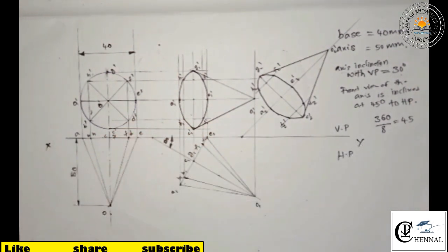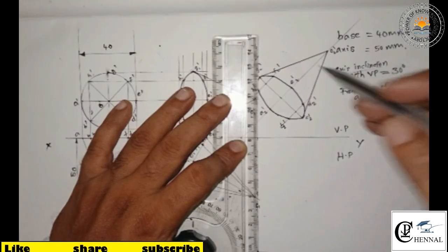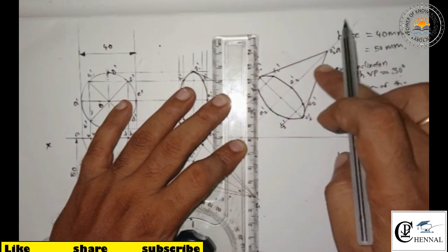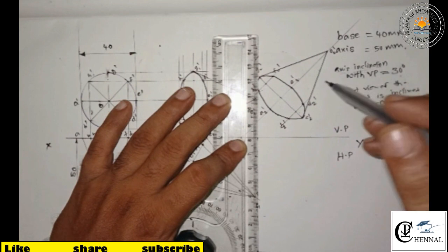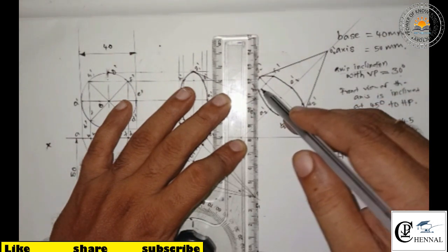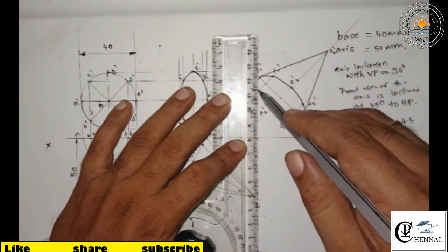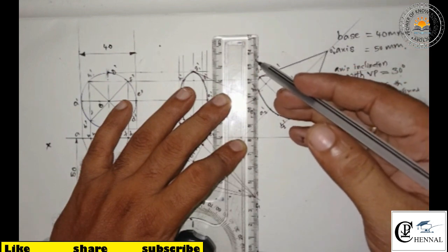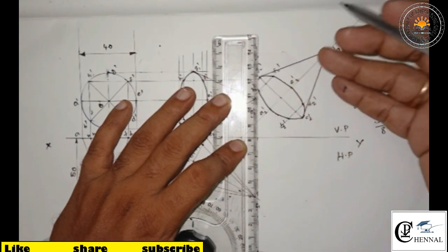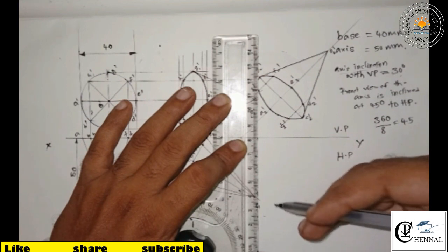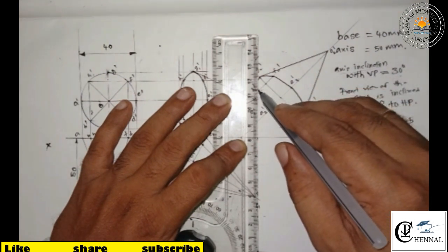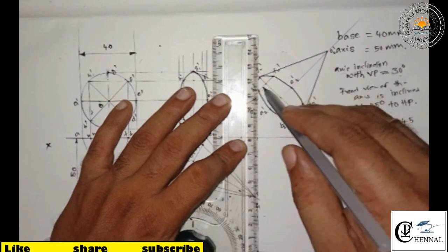Okay, draw perpendiculars from the recreated front view. This one is the recreated front view. So now I need to obtain the top view. How? By drawing the perpendicular lines from the front view to the horizontal plane. Okay, so draw the perpendicular lines.